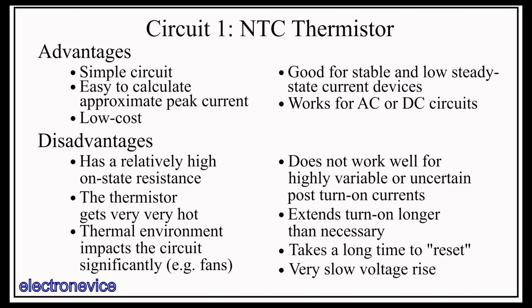Additionally, if you have to size the thermistor to be able to handle the maximum current, and it's only running at maximum current a small portion of the time, then the thermistor will have a relatively high resistance at the lower currents, resulting in power losses.